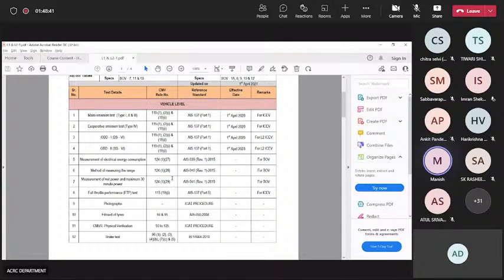So they check your vehicle on a dyno, they keep running your vehicle in the IDC cycle. They'll start from zero, they'll stop, then they'll climb up to 40 kmph, then they'll go down. Again the cycle will keep repeating until your battery goes from 100% to 0% SOC. Then your range will be defined as per ARAI. But real world range will be defined by the real world application. There your range will drop, definitely it will drop 25 to 30% depending upon the vehicle application. If there is a high speed vehicle going beyond 100 kmph, then definitely your vehicle range and ARAI range will have a lot of differences. So that range will be defined by ARAI, that is one part.